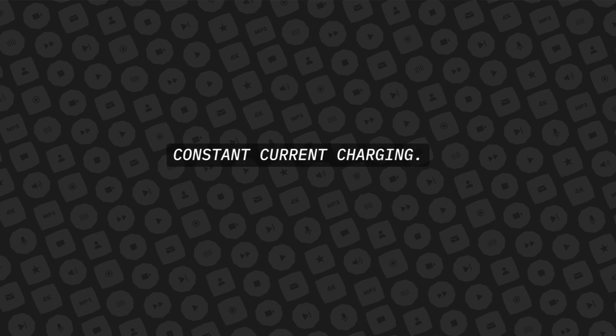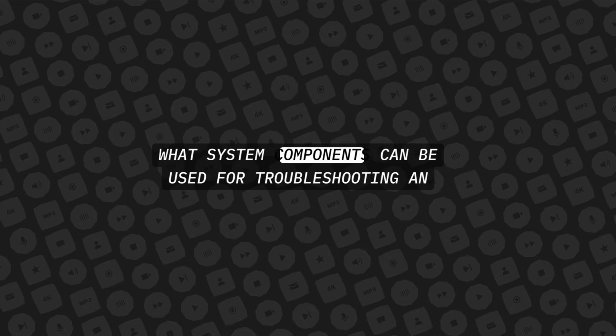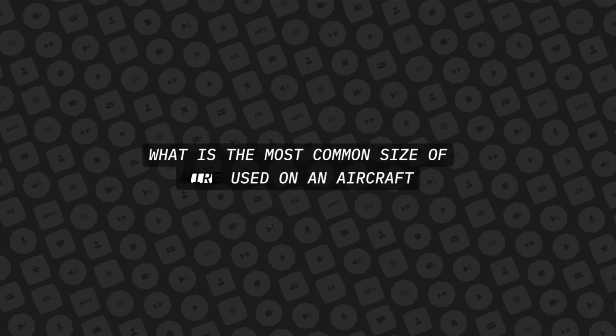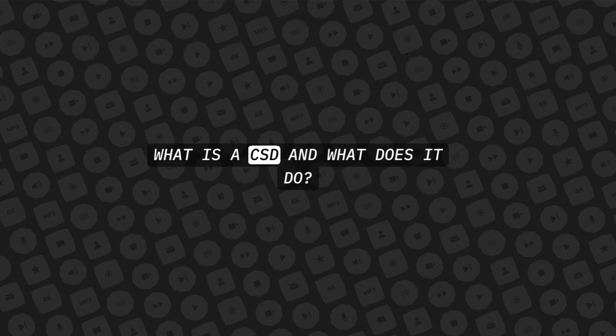Constant current charging. What is the max allowable voltage drop from a generator to a bus bar? 2%. What system components can be used for troubleshooting an aircraft electrical system? Voltmeter and ammeter. What is the most common size of wire used on an aircraft electrical system? 22 gauge. What is a CSD and what does it do?